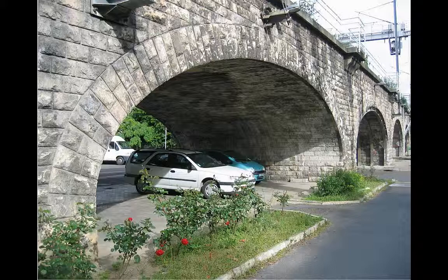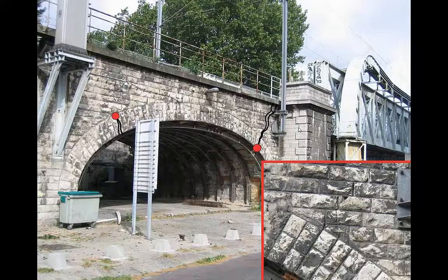So the next example is, I think, the first bridge I ever applied this functionality to. It's a railway bridge in Paris. There's an approach viaduct to a river crossing, actually crossing the River Seine. And what appears to have happened is that timber piles supporting the approach piers have gone rotten, and we have evidence of quite severe settlement and corresponding cracks.